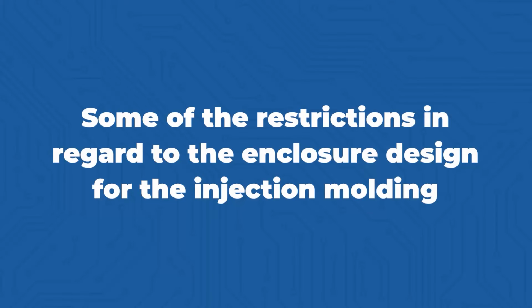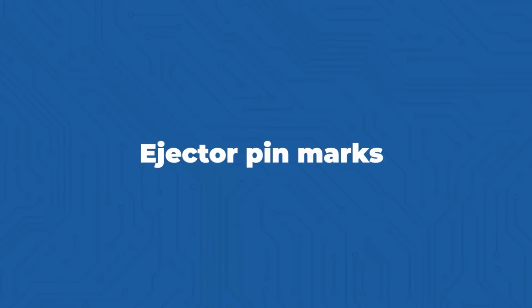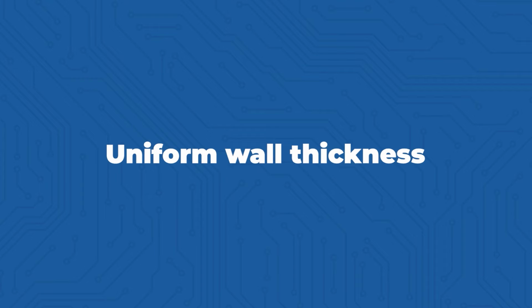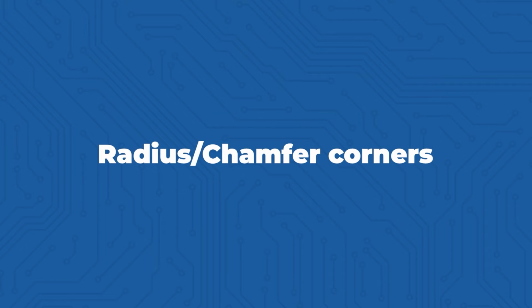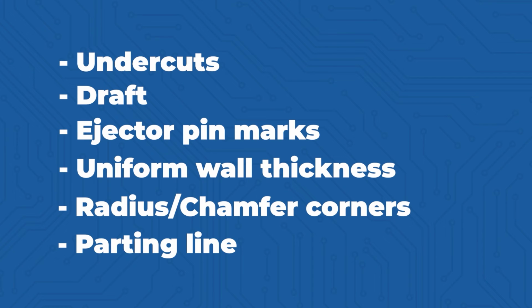Some of the restrictions when it comes to enclosure design or any part design for injection molding are undercuts, draft, and injector pin marks. You have to have uniform wall thickness, radius or chamfer the corners, and there's a parting line. I'll go through each of these in detail. But let's first take a look at a 3D model, because this is where it all starts, with the 3D model.